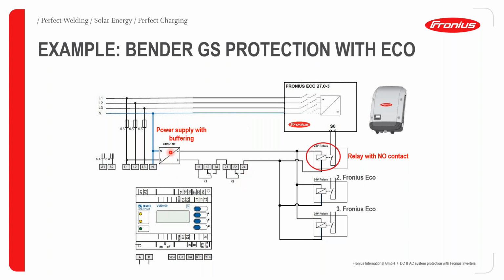Meanwhile, an AC to DC converter can be used in this case to provide power and buffering to the relays. So in this case, we're using a 24 volts AC-DC converter because of the specification of the relay in this particular example. So how does this work? So once there is a fault or any necessity for it to trigger, which is of course a fault, the GS protection device, of course, sends the command.